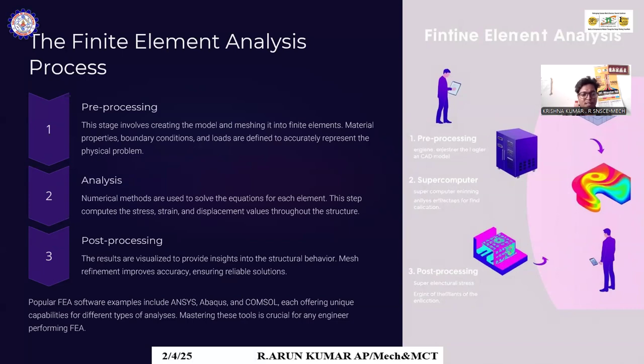The second stage is defining the analysis we have to do. Either we go for thermal analysis, CFD (computational fluid dynamics) analysis, or static structural analysis. Whatever you want, you can choose that type of analysis. The second stage is called analysis. Numerical methods are used to solve the equations for the elements. This step computes the stress, strain, and displacement values throughout the structure.